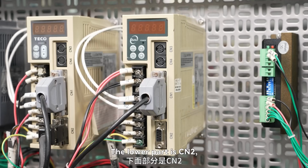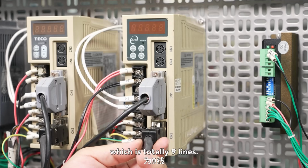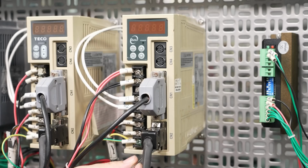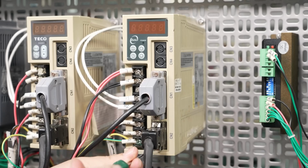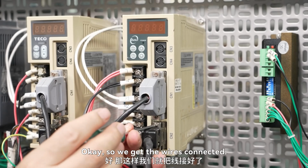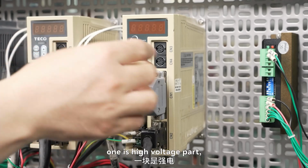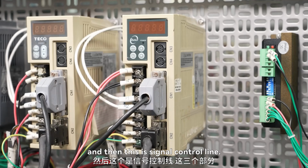The lower part is CN2, coming from the encoding line of the frequency converter, which is totally 9 lines. The encoding line comes from the frequency converter connected by the encoder, and the encoder acquisition signal line is connected here. Okay, so we get the wires connected. In fact, it is divided into three parts. One is high voltage part, the other is computer coding line, and then this is signal control line.